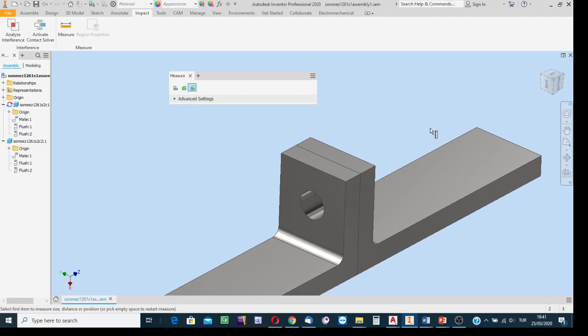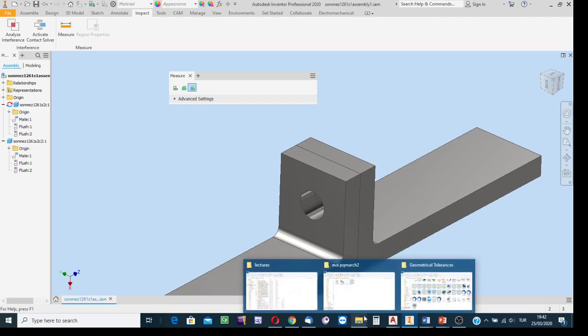Okay, this means the length of the bolt should be sufficiently long to extend through both of the holes, and to have a further extended part beyond the surface of this component to use for screwing the nut. Well, onto the total thickness of the components, we need to add the thickness of the nut, and also the thickness of washers.